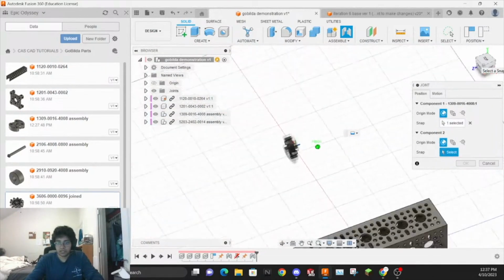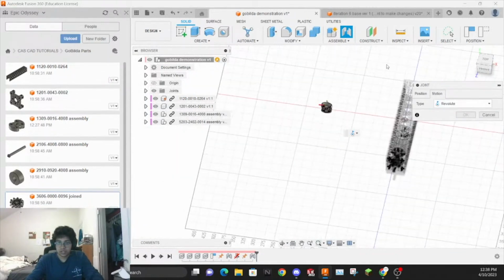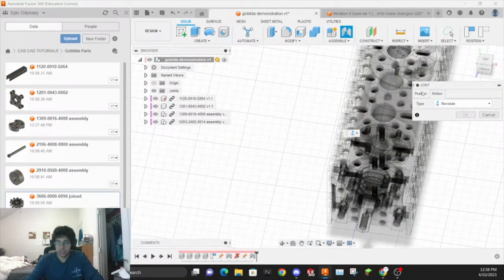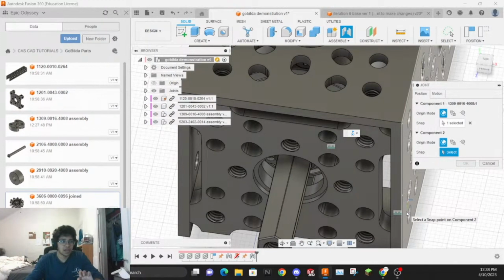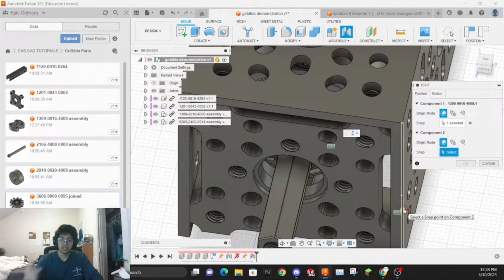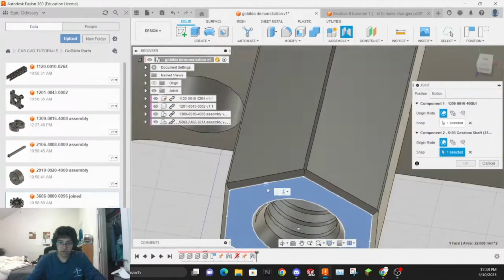One important thing to note is that you want all of your points to be centered. So when you saw me attach the quad block to this hole here, I was finding the center of the hole of the quad block that I wanted to attach to the center of the hole of the U channel that I wanted to attach. That keeps everything very strict in its position. So make sure you remember that.